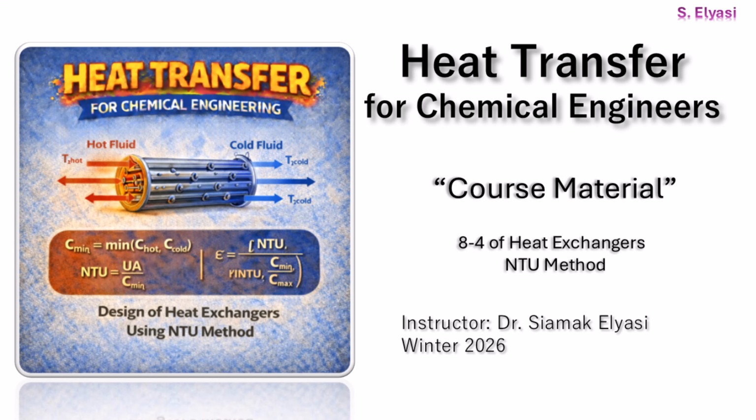Just think of NTU as a measure of the heat exchanger size. It's the product of the overall heat transfer coefficient and the area, that's UA, all divided by that Cmin we just talked about. It's crucial for comparing and selecting different exchanger types. So these 3 variables, effectiveness, capacity rate, and NTU, allow you to analyze heat exchanger performance explicitly, without any iteration. Let's dive into more detail.